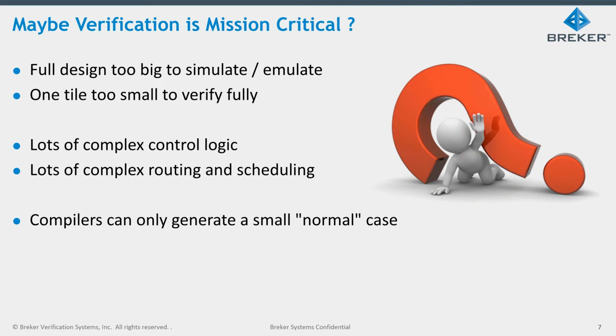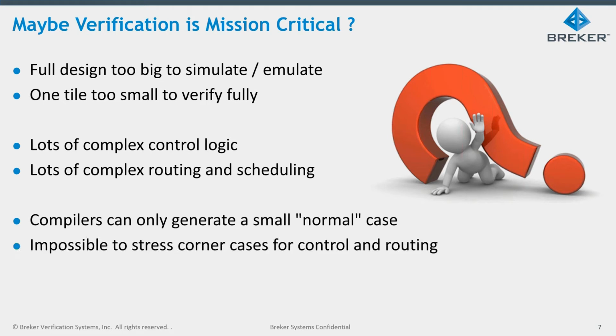We have no idea what the compiler is spitting out and what the logic behind it is. And it is not possible for that to stress the corner cases for the control and routing that we care about. So to do a good job, we really want to be able to generate synthetic test cases that are focused on doing what is likely to break in hardware.